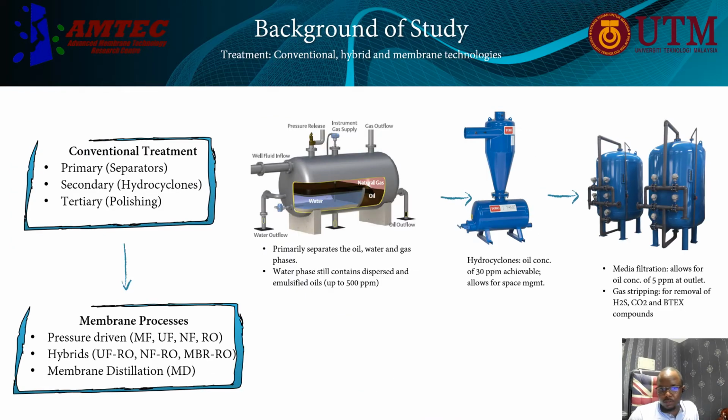So here we quickly look at the background of this study and try to make a case for why researchers have piqued interest in membrane distillation as a technology for produced water. Conventional treatment processes have seen the primary, secondary, and tertiary treatment stages, where you could have produced water oil content down to as low as 5 ppm at the end of polishing and stripping, and you are basically left with water that is hypersaline.